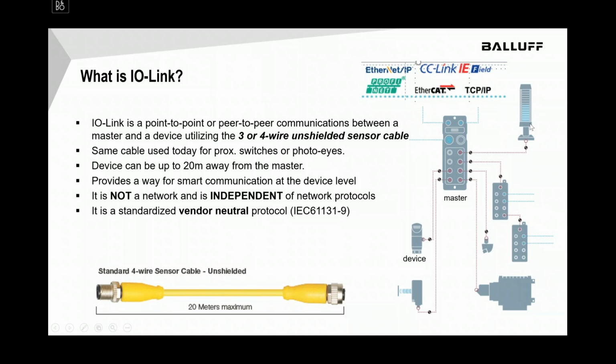And it is completely vendor neutral technology. Defined by IEC 61131-9. So it's a standard communication. It's nothing proprietary to Balluff or to any of these vendors. It is a completely vendor neutral technology. So you can have anybody's masters with anybody's devices and they should be able to connect as long as they are I/O link.